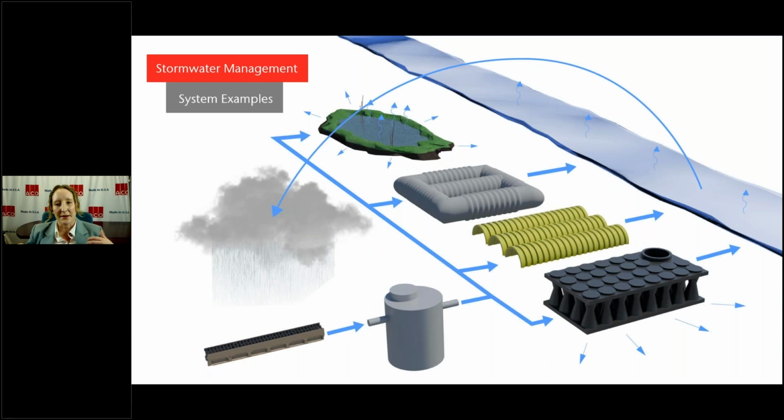That system is either a corrugated metal pipe system. Also, it can come in the form of a precast concrete pipe system. Other systems in this category include cast-in-place or precast concrete tanks. These systems typically have a high void ratio. And when I say high void ratio, I'm talking about the percentage of space in that system available for stormwater storage. So higher void ratios equals lower excavation in those systems. They're very structurally sound, but they can be costly to purchase, deliver, and install.